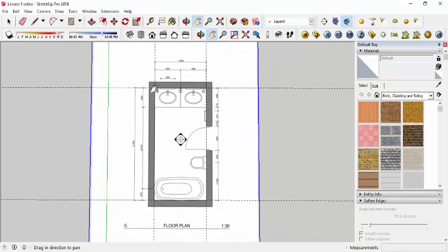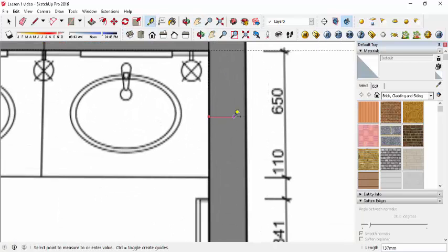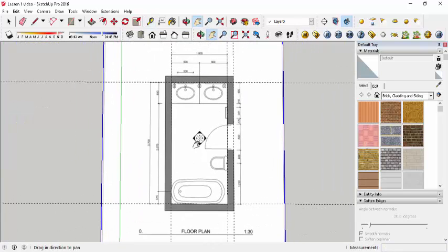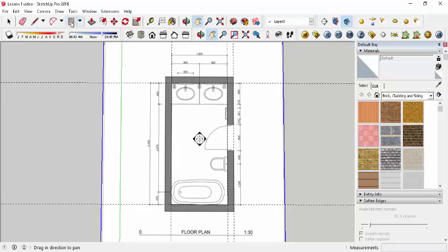we will do the wall now. For us to do the wall, I usually start inside and then offset the thickness of the wall outside. This wall is 200. That's 197, but if I hit 200 on my numeric pad and hit enter, that's 200. So that's the thickness of our wall. To create the wall, click on rectangle and then click one corner, drag it to the other corner. It will snap right to your guidelines.